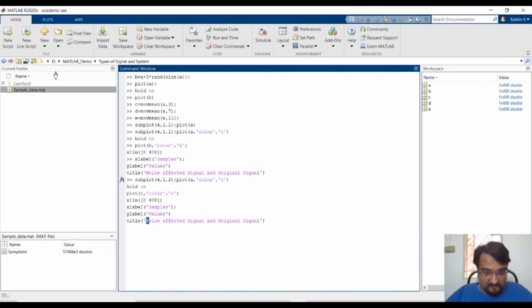This would be the 3-point moving average, right? When I say moving average, there are different types of moving average, known as weighted moving average and exponential moving average, but this is a simple moving average where we are not multiplying it by any number. I mentioned that MAC thing, right? Multiply and accumulate. Here we are just using a simple moving average, okay, with 3 points. So let's quickly see how that graph looks.